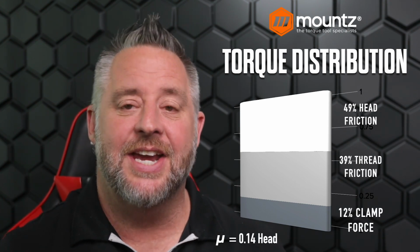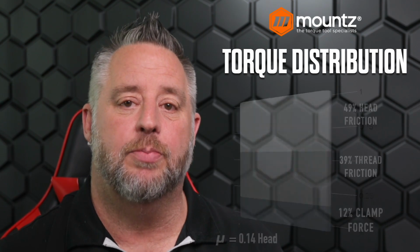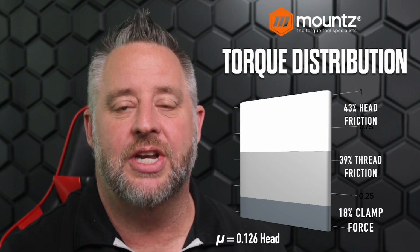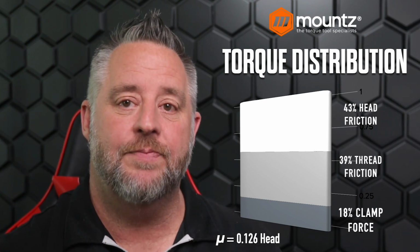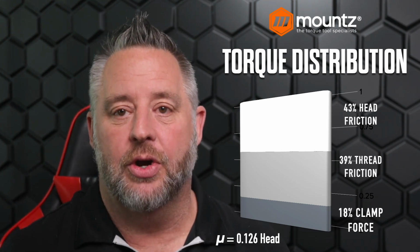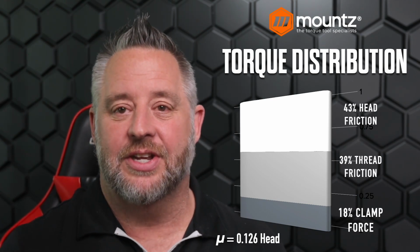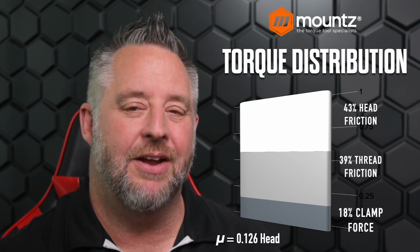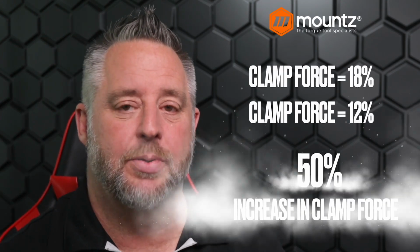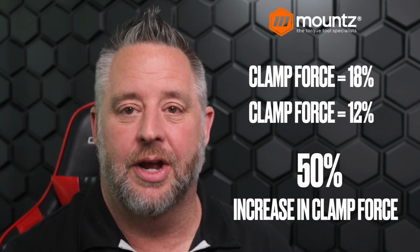And so in that case, it would reduce our head friction. In this case, we go down to 0.126, which would be a 6% reduction in our head friction distribution. Our thread friction would remain the same. However, our clamp load would increase by 6%, and again, causing us an issue where we may be putting that fastener past its yield point. And so that's going to be a 50% increase in our clamp load for our particular application.